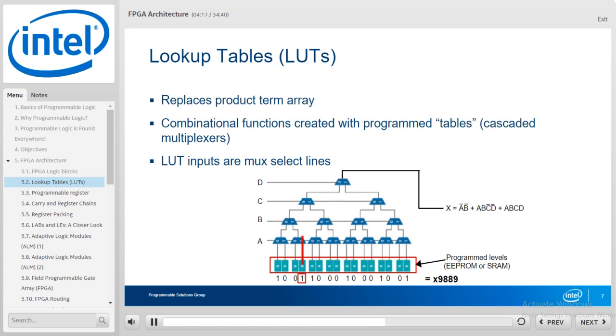As an example, this minterm is routed through the LUT where A and B are high and C and D are low. This particular minterm corresponds to this product term in the desired logic function. While it may seem like more logic levels are required to produce outputs on a LUT versus a CPLD macrocell, the flexibility of function creation and LE chaining, which we'll look at in a moment, provide improved performance and help to minimize wasted resources.